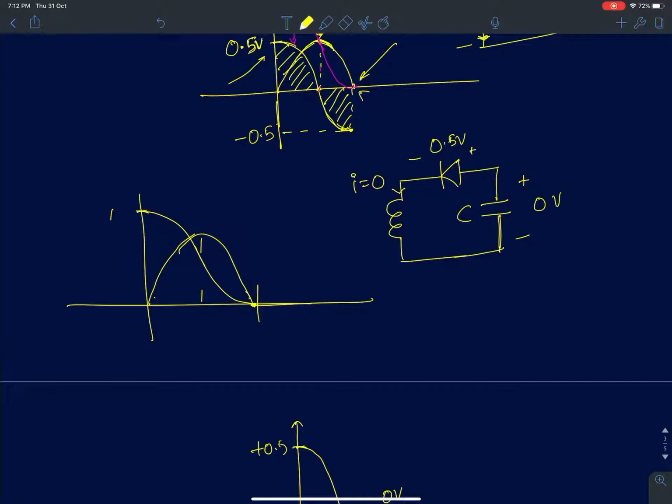So now the diode model, where we assume that the model for the diode is something like this. For any voltage greater than V gamma, it can conduct any amount of current with just a voltage of V gamma across it. So here we have modeled the diode as a voltage source of value V gamma, but we know a diode can carry current only in one direction. Current can only flow from positive to negative terminal. So which means the diode will always absorb power. I can also say it will always dissipate power. Okay, so that's where the power gets dissipated.